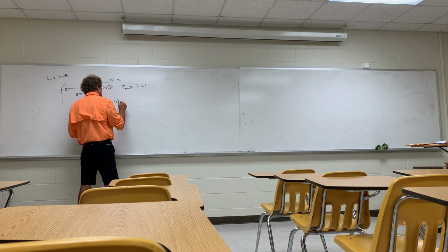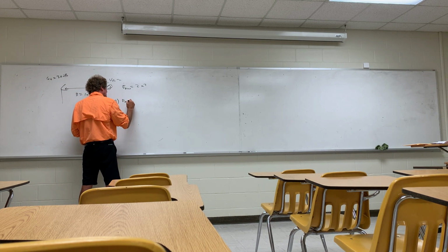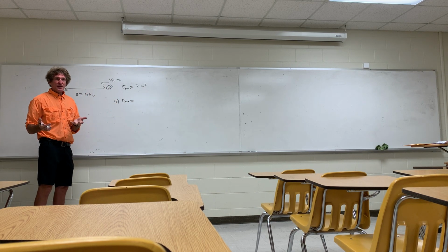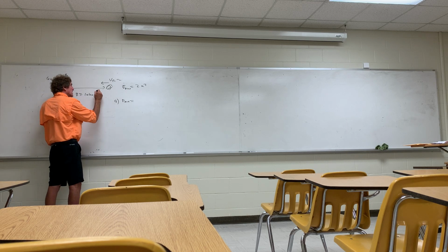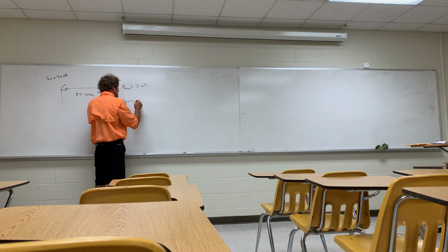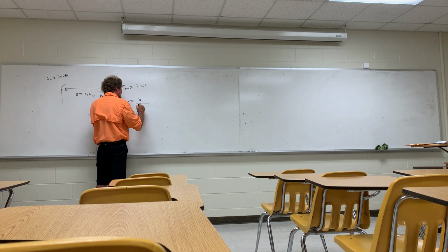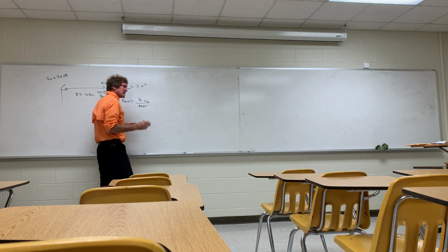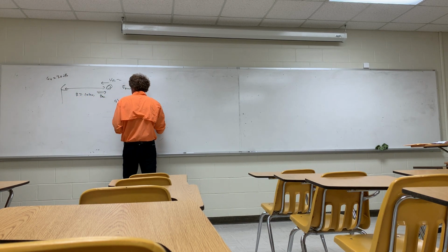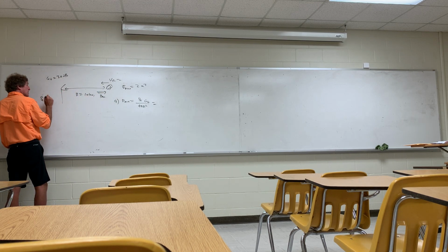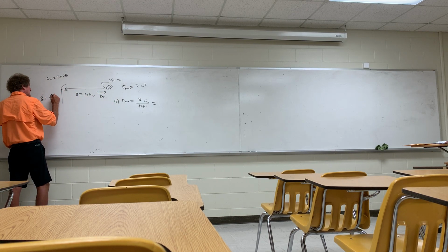Right. You are always going to get that question from me. I always make sure people know this. So first I want to find the average power density on the target, and that's always going to be transmitted power over 4 pi R squared times the gain of the transmitter. That's the linear gain. So I think that was 30 dB. So transmitted power, I forgot what it was. 40 kilowatts?